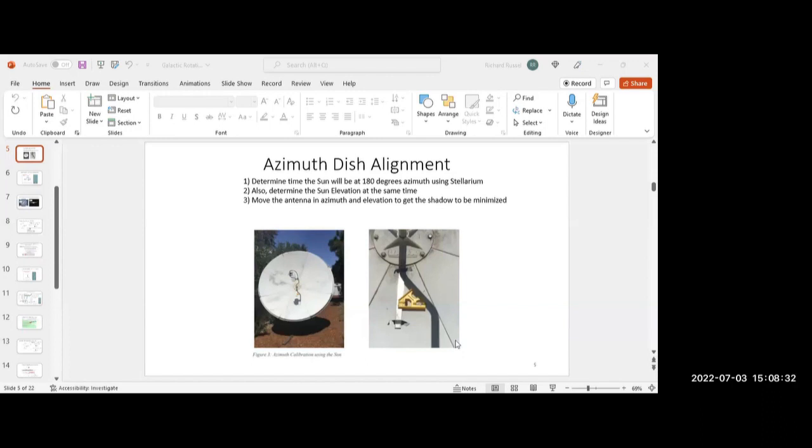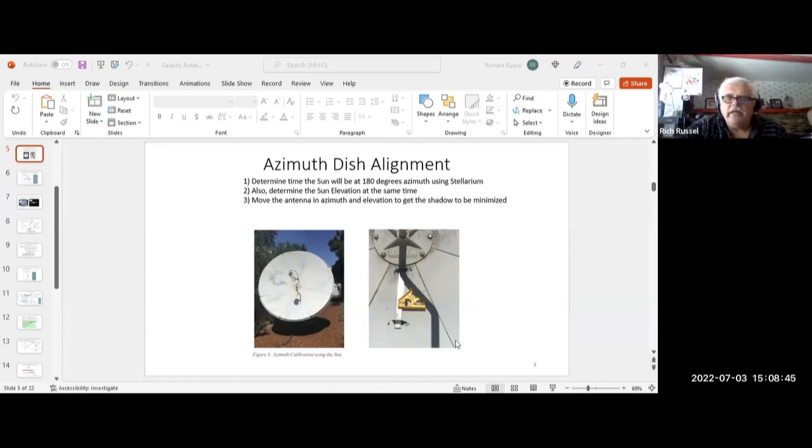Hi, this is Anthony. Question on the SpectraCyber hardware and software. Does it support multiple receivers and multiple antenna feeds, or is it just one antenna feed and one LNA? Well, it has a down converter. It down converts to IF. It has its own receiver, and so my belief is it'll handle 1420 megahertz feeds from any source coming into the back with one input, and then it'll do the scan across there.